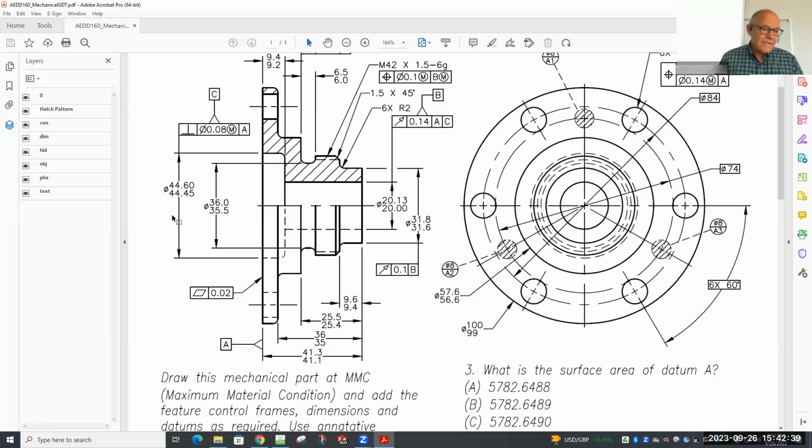Well, machine tool is another matter. In machine tool, we deal with tolerances that are sometimes as small as a tenth of a thousandth of an inch. So if I had hair and I could pluck one off my head, which I don't, and then I took that hair and I split it into 30 parts, I'd be talking about a 10,000th of an inch. So we're talking here about very, very small tolerances sometimes, not always.